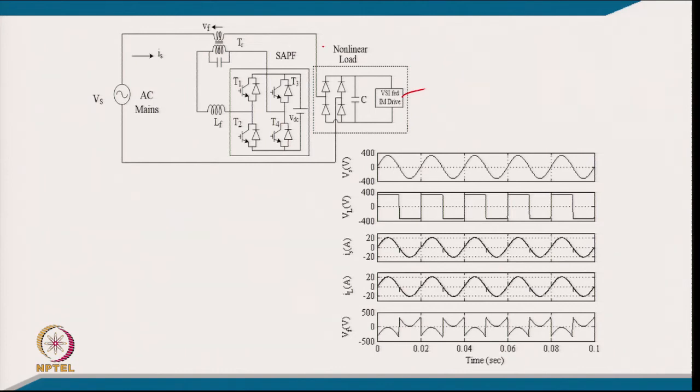So, now in that case when we are forcing a sine wave current into the diode rectifier, you will find that typically this DC link voltage will reflect here at the PCC as a square wave. So, with that, after making a model and a complete simulation with realistic, actual data.